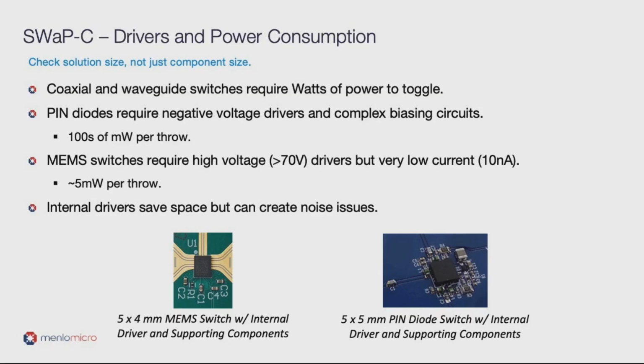MEMS switches, on the other hand, require high voltages around 70 volts to operate, though at very low current output. One last thing to note is for parts that have internal drivers, they can affect the noise performance of the switch. So in applications that are sensitive to noise that might come from internal regulators or digital circuits, a good idea is to select parts with external driver options.